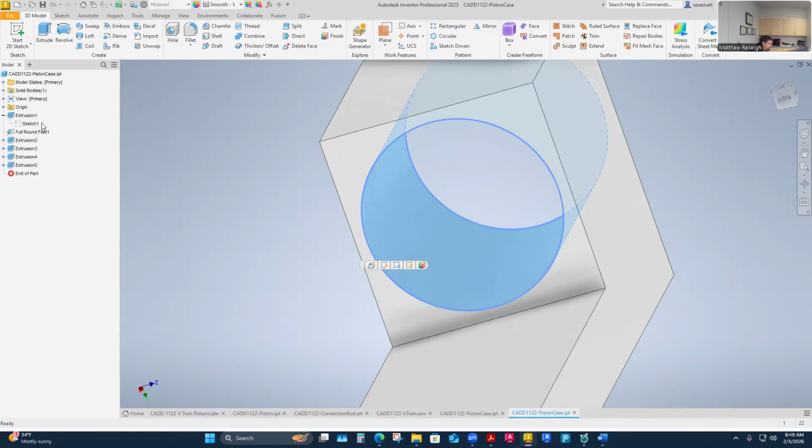I think I measured the one that I sanded a little bit, and I kind of got an idea of where I was at, and that was just a great guess. I did some really light sanding on the inner bore, because when 3D printers print, they can leave a little roughness. So I just barely sanded that, and I barely sanded the outside of the piston a little bit, and it fit in really good.